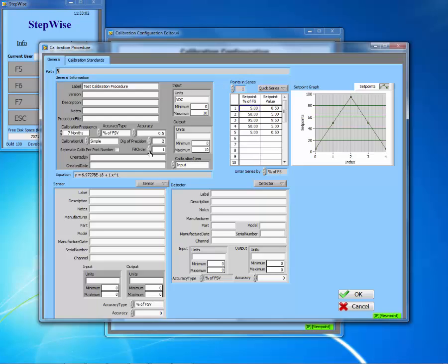The accuracy of the percent error acceptable is defined in the accuracy field, where the number entered is the percentage. This number translates to being the percentage of the voltage range being tested. In this case, that number is 0.05 volts because the range is from 0 to 10 volts and the acceptable percent error is 0.5%.